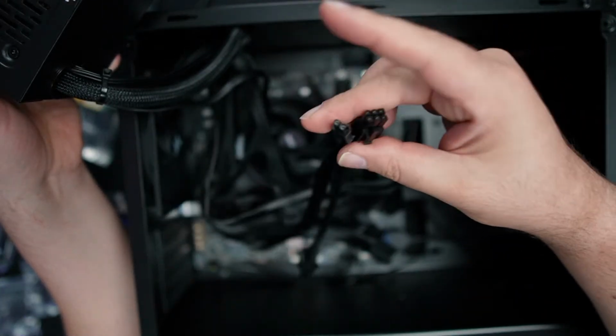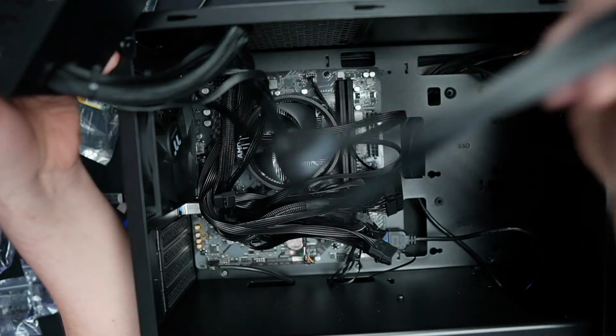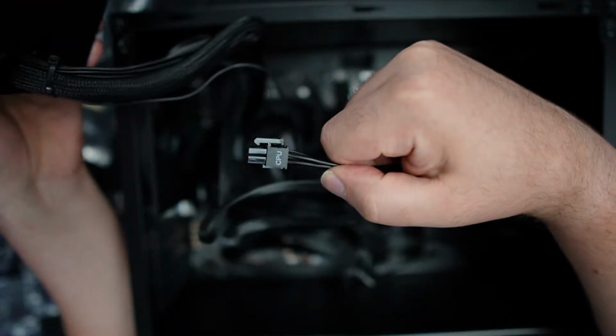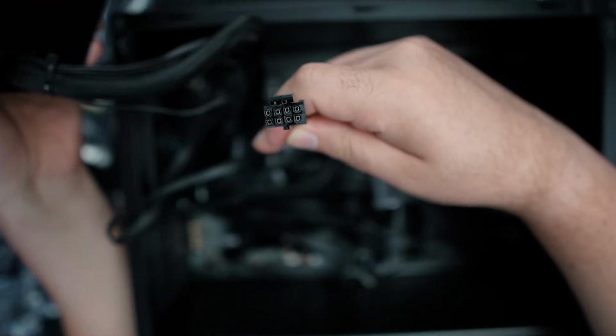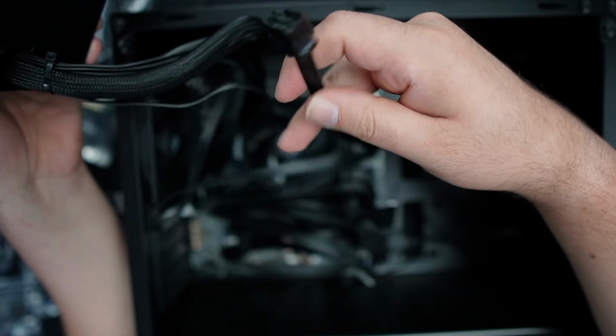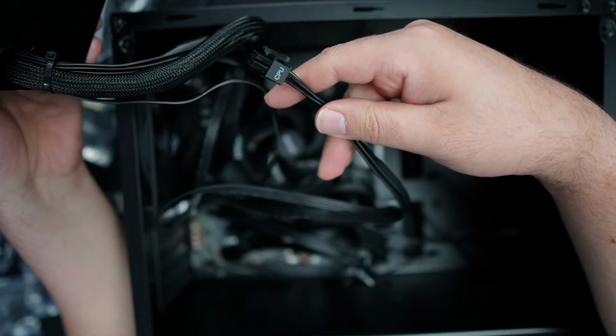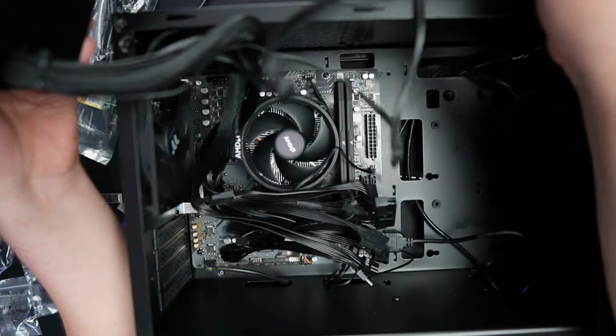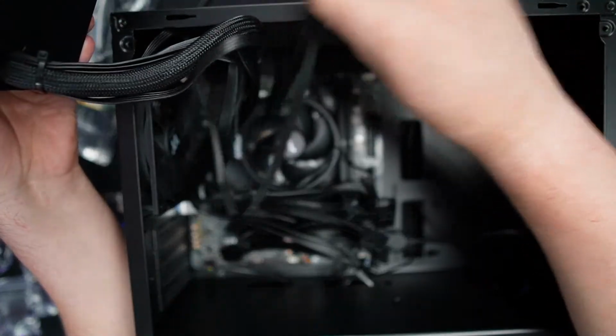Same thing for this cable. It's just another braced off cable. You can use the same thing on the same channel. It really doesn't matter. Now, going down to this, the CPU one kind of looks like the PCI Express one. So it is still 8 pins. Do not get these confused. Be sure that the CPU one goes down to the motherboard. Do not plug the PCI Express one into the motherboard. That would be a bad problem. You get too much voltage.